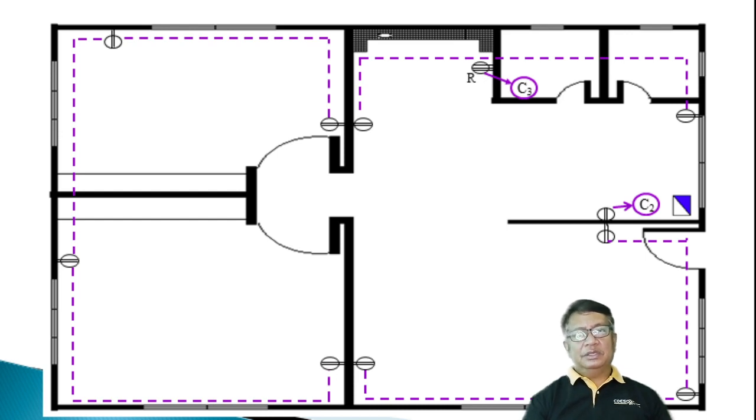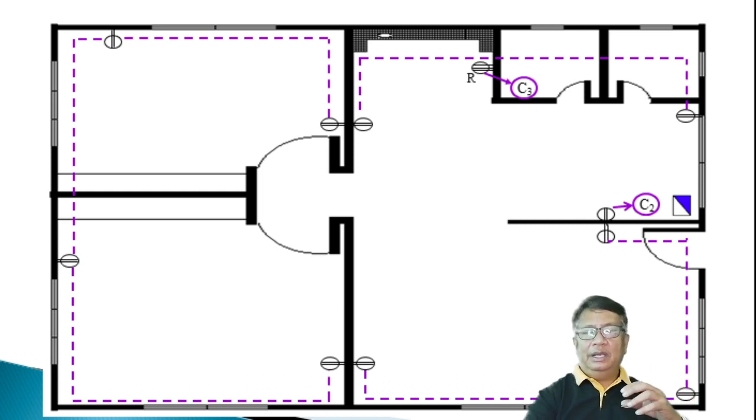But I suggest that you separate the floor plan or layout for the convenience outlets and special outlets, and also separate the electrical layout for the lighting outlets. Why? Because it will become crowded, and the electricians who install our plan will find it harder to understand the connections because of the crossing of the wires.